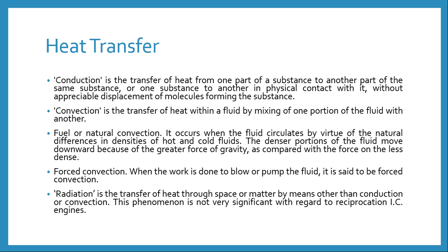When we talk about natural convection, the fluid circulates by virtue of the natural differences in densities of hot and cold fluid. The denser portions of the fluid move downward because of the greater force of gravity, as compared with the force on the less dense.